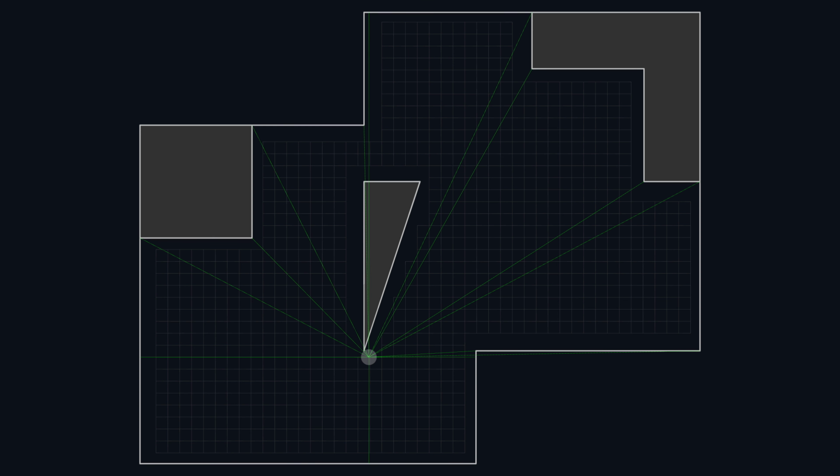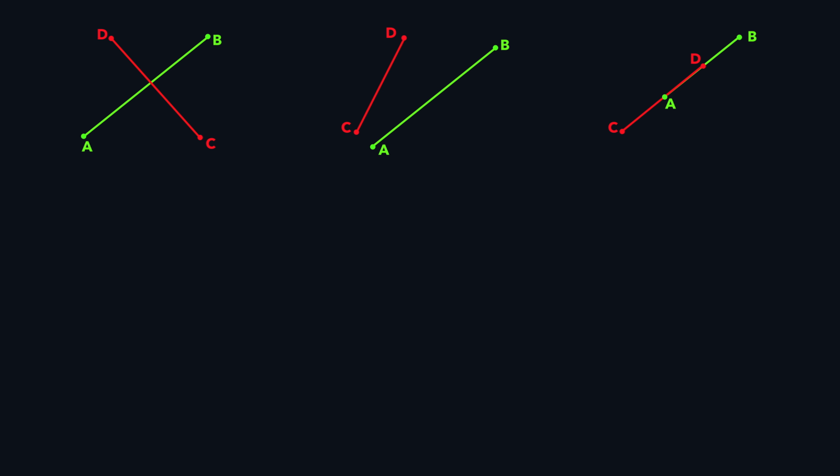If we could calculate the distance from the edge to every edge of the obstacles and the room, we would simply take the minimum of these distances to find the closest edge where the problem might occur. So let's look at how to calculate the distance between two edges. In other words, we want to find the distance between two line segments. Two line segments in a plane either don't intersect at all, intersect at one point, or intersect infinitely many times. If they intersect at least once, their distance is 0 because they share a point. If the segments don't intersect, calculating the distance is more interesting.